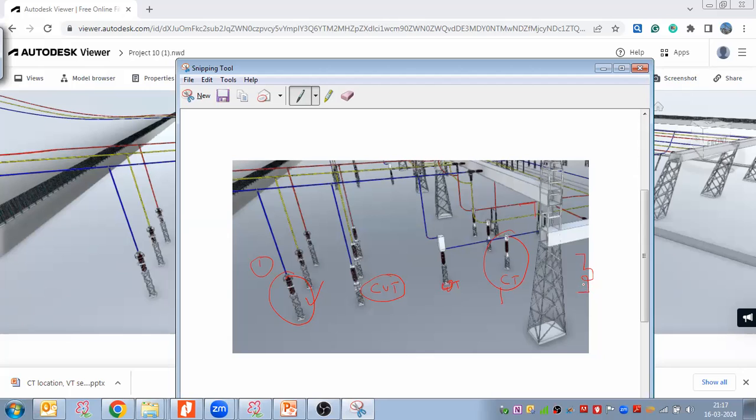In the primary winding, we take just one winding, or the conductor itself works as the primary, and after that we have the secondary windings. We discussed that in substations we take the multi-core and multi-ratio CT. So when it comes to CT sizing, we have to do the sizing core-wise. That is what we have discussed so far, right?